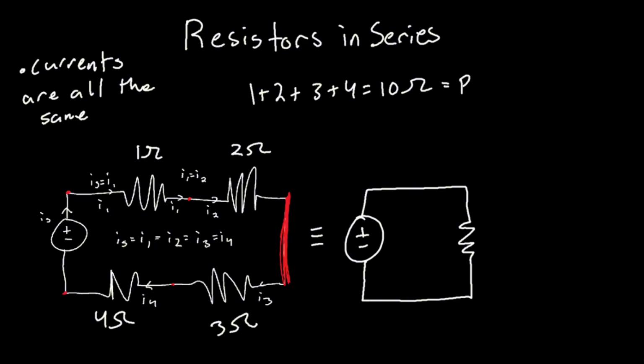Well, 10 ohms is what we call the equivalent resistance. So if you were to just cut off this part, the left and right portions of these green lines, and say how the electricity flows through on each side, then basically what happens is the circuit only sees all the resistances as just simple 10 ohms combined together. So however much the voltage drops throughout each of these resistances is the same as however much just a single 10 ohm resistor drops the voltage.